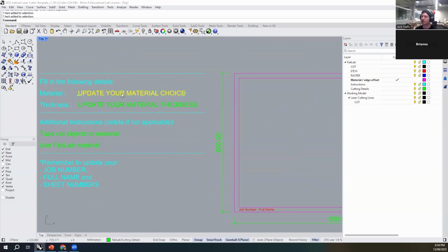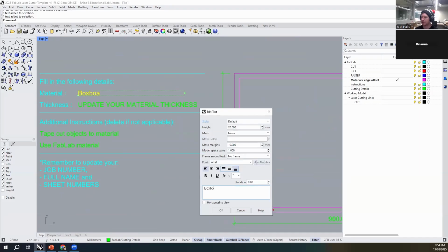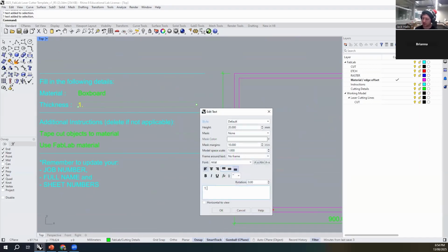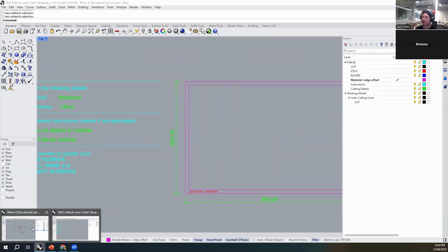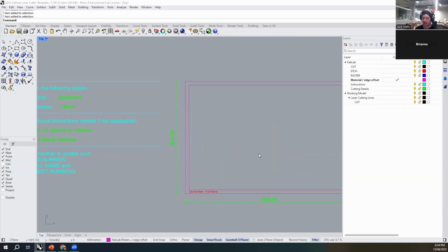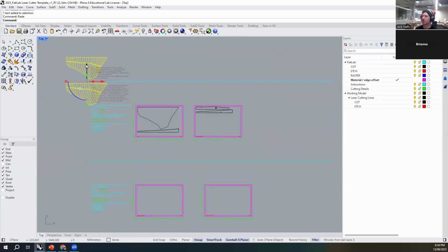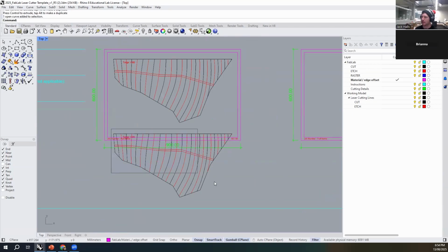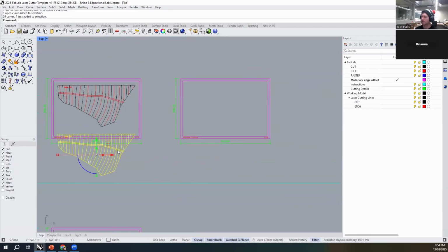So if we were moving on to our 1.8mm box board, I'd set it to 1.8mm, and then repeat the process. This is our 1.8mm geometry. Control C, paste in my command line, and drop that here. These are quite big pieces, that's fine. Drag in just that section.